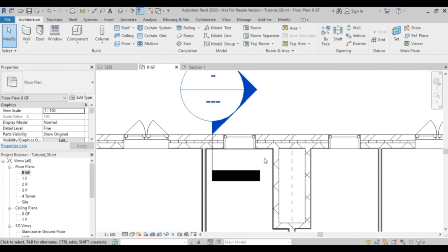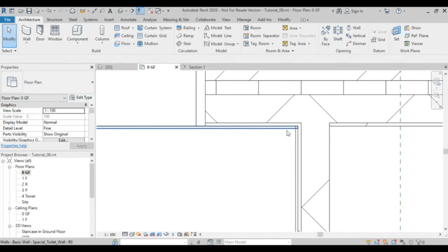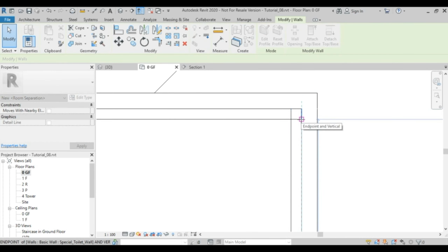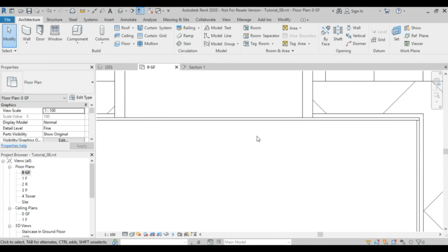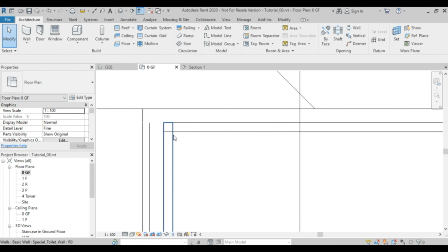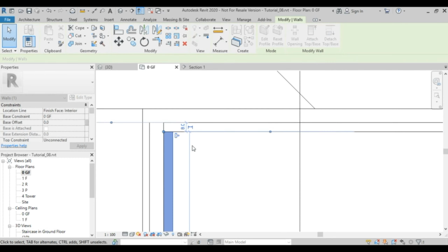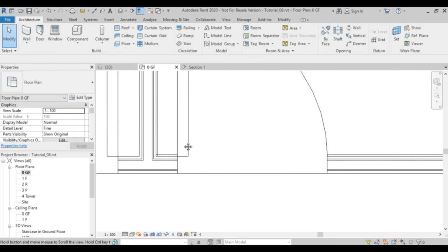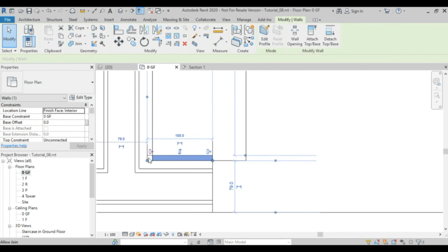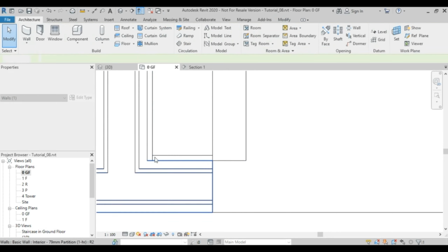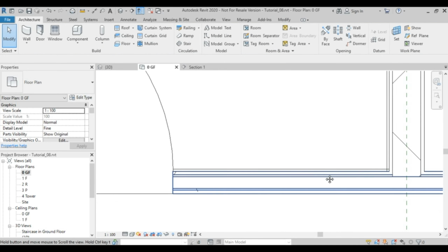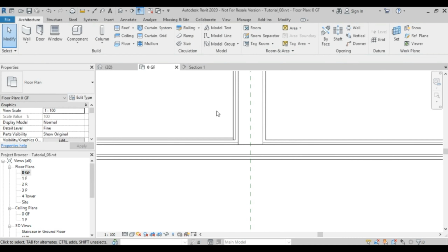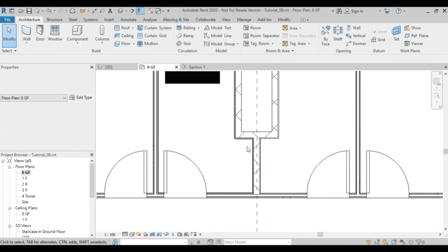Now the four things, now we can manipulate it by simply doing that, as if the walls are actually stopping at each other. Other than that, you are leaving things to Revit to control, but this way I'm actually controlling it by myself, because it's only the thickness of the terrazzo or the mosaic.